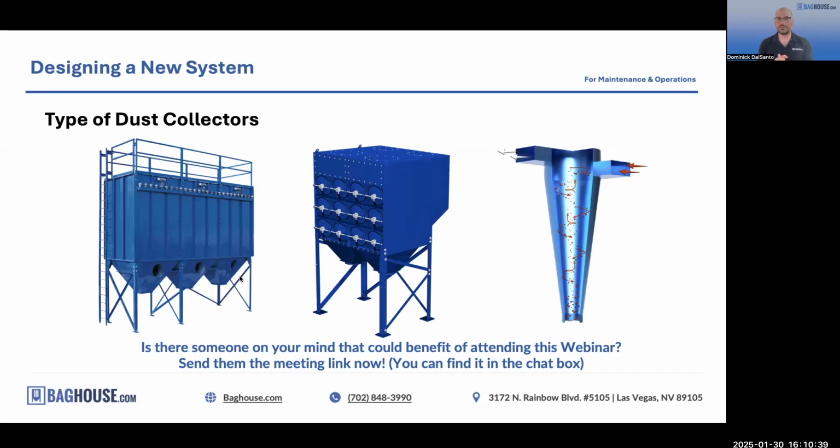So a cartridge collector, they're great. We use them in a lot of applications, but they're really more like a van, like a minivan. If all you're doing is moving a small group of people around all the time, it makes more sense to have a van than to have a big pickup truck, right? But you would never use the van to try to pull a big trailer to go off-roading, right? It just wouldn't work. And the same thing happens with cartridges a lot of times. They get stuck places where they have no business being, either because it's the only thing the sales guy has in his rep, in his thing that he reps, or because everybody else wanted a bag house and he wanted to be cheaper, so he tells you can use a cartridge collector.